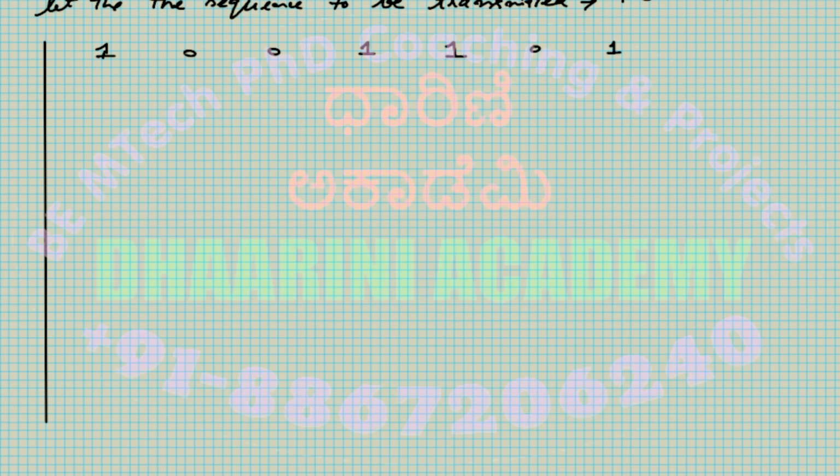what is the duration of each bit. So I'm going to send one for this much duration. You fix it; for the complete communication, it has to be fixed. Like I select maybe 2 milliseconds. In 2 milliseconds, I'll send one. The next 2 milliseconds, I send zero. The next 2 milliseconds, I'm sending zero, next zero, and so on. So this has to be decided.